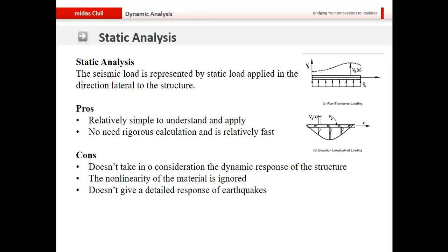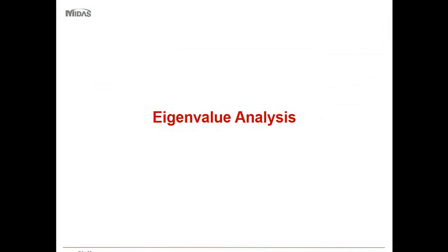So we don't get the full range of the steel and the concrete during these types of events, and it doesn't really give us a detailed response to an earthquake. It is a very simplified method of simulating those types of loads. So sometimes it's used, sometimes not so much, depending on the location of the bridge, but it is one of the types of analysis.